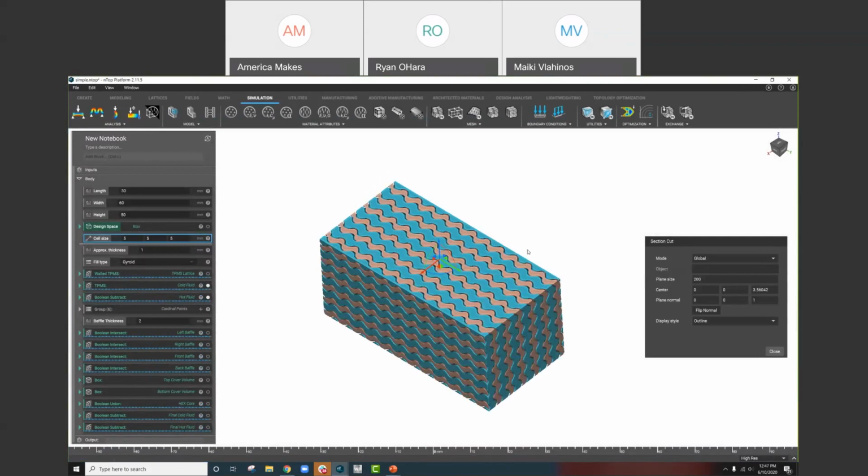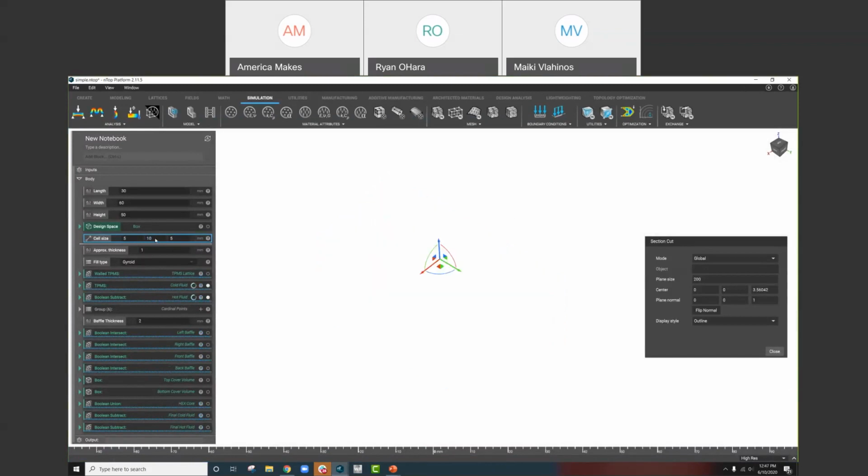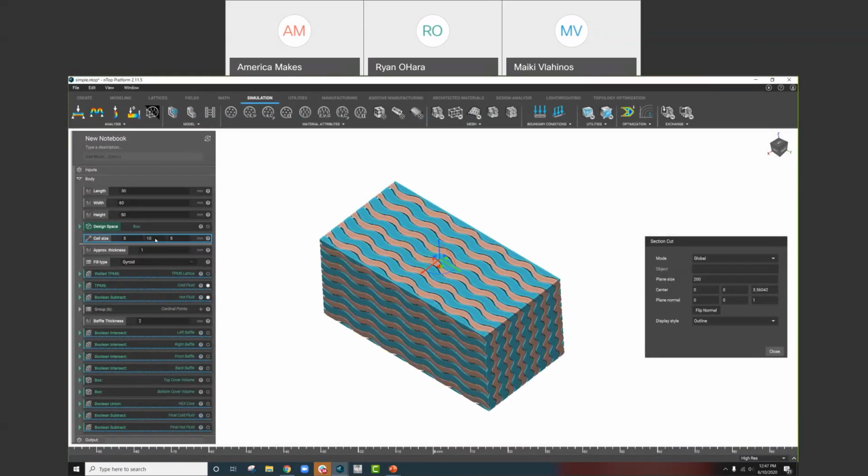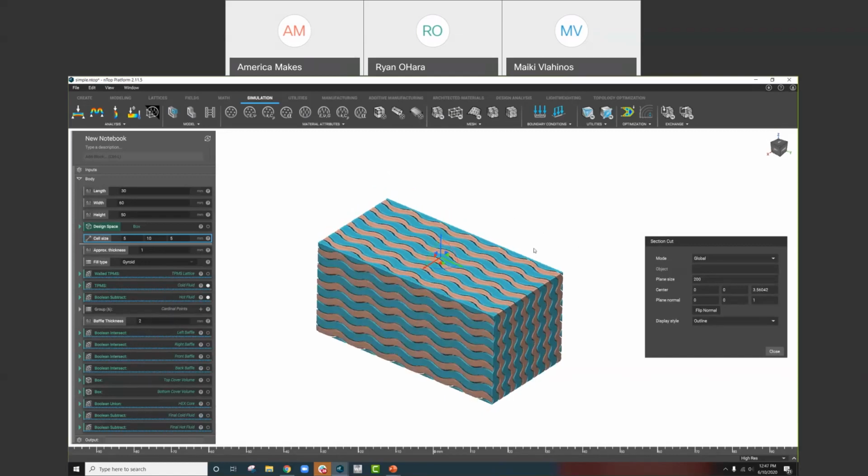And we saw a very substantial drop in pressure as soon as we increased our cell size by a factor of 2. It was quite remarkable. So what we're looking at now is, let's maybe hover around an aspect ratio of 2 and do a further deep dive into what this looks like.